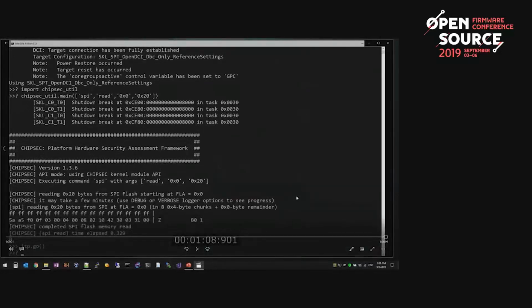This is kind of awesome if you tend to deal with the SPI often, but a caveat is this is very, very slow. If you want to dump the whole SPI using ITP, you better go for lunch. Probably about an hour for 8 megs. But anything chipsec can do, you can do with ITP. At any point, you can halt the system, which is at any point during boot, which is pretty powerful. From the reset vector onwards, it's up to you.